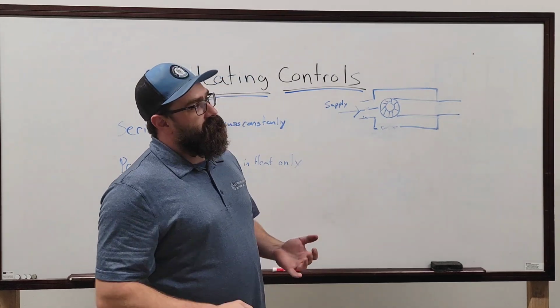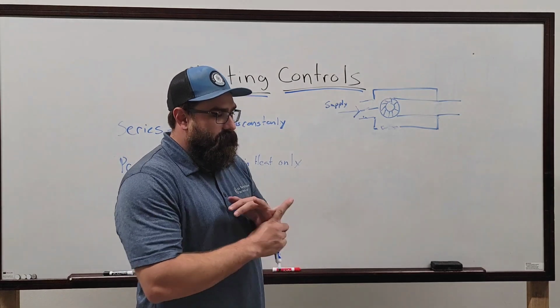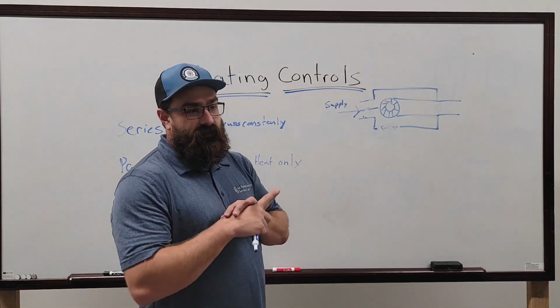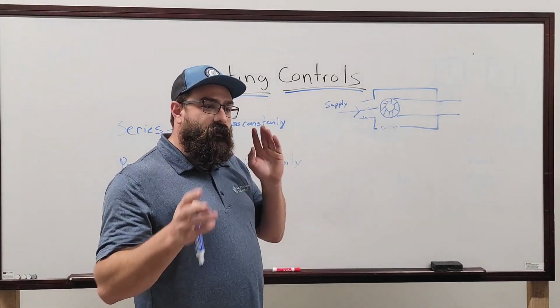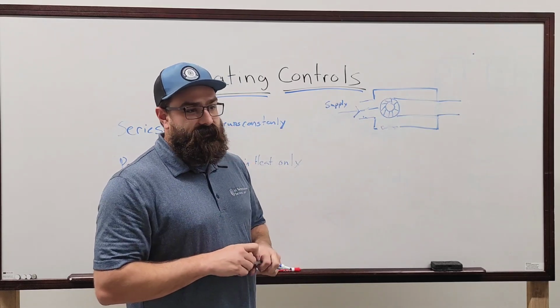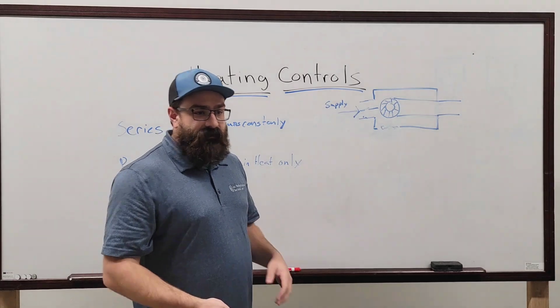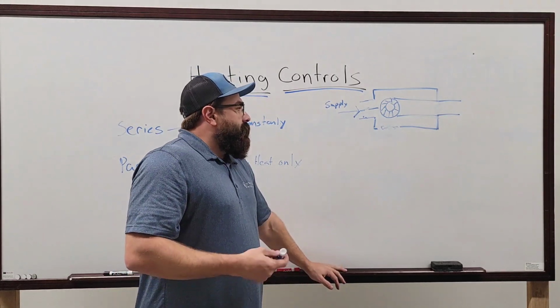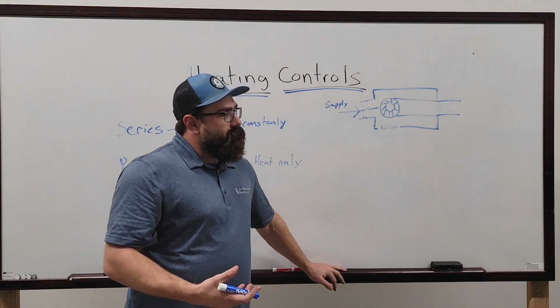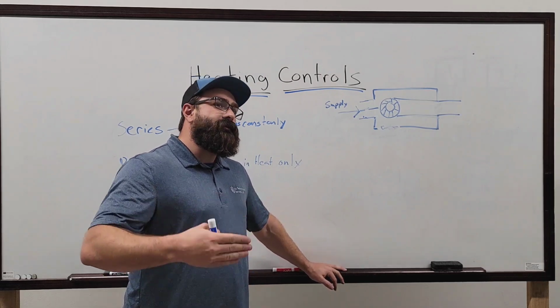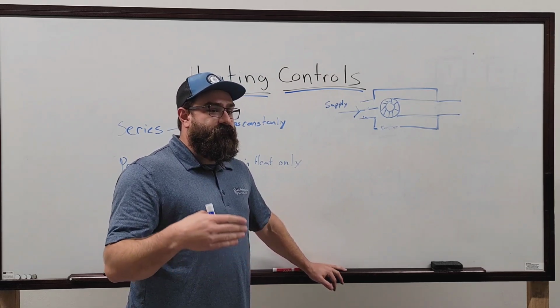I like series boxes for 3 reasons. A, the customer does not experience a fan turning on and off. They don't hear that noise difference, which is a huge deal in these big buildings, especially now that they're going to open ceilings and stuff like that. They hear the noise.